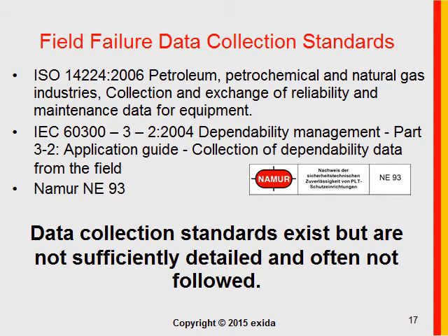Why are there all these problems? Aren't there field failure data collection standards? Well, yes. IEC 61508 refers to ISO 14224 and IEC 60300-3-2. And there is also the NAMUR NE93, and they all do set up a framework for data collection.